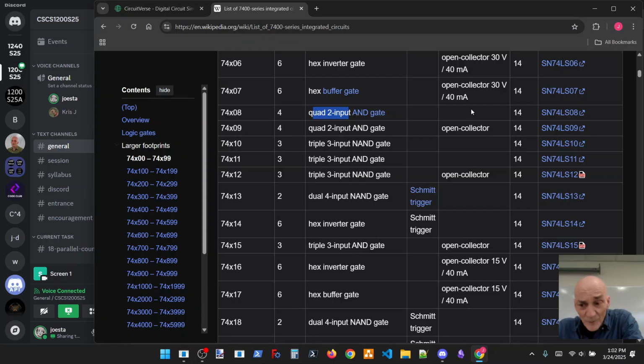Well, electronics people had a couple of ways of dealing with this. One of them is this open collector thing. If you have open collector outputs, you can connect them together. Someday, if you want, I can go into more on that in the electronics and what this collector thing is all about. It actually has the transistors in the chip. But for the moment,